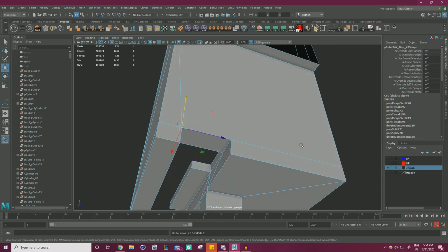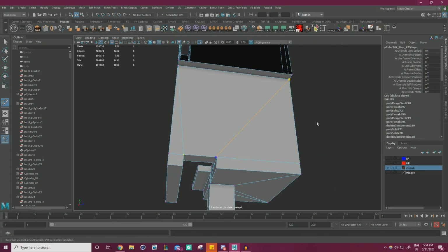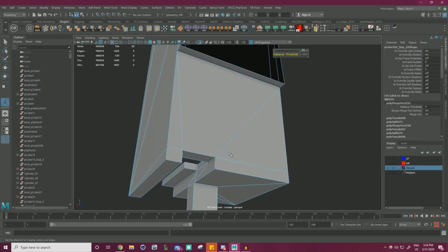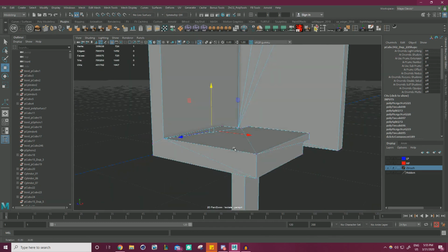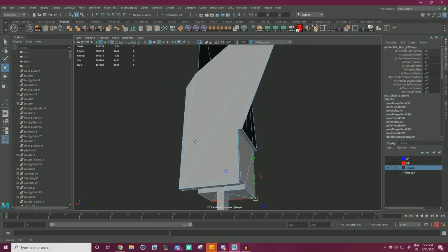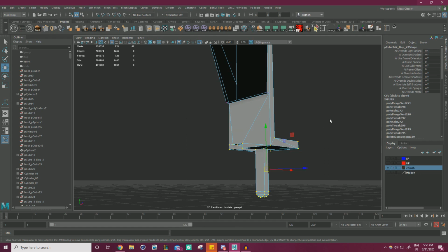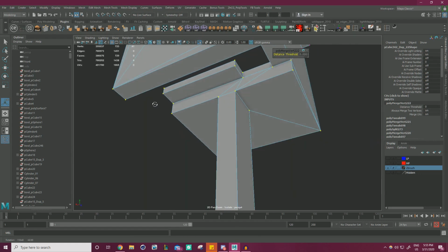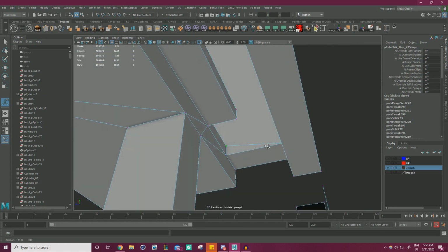Of course, over here, it's still going to be a problem because we don't have a similar situation going on over here. So with those guys anchored down, that should take care of that. The stuff is all as it should be, as long as I snap that down. Yep, that's all proper geo. Just making sure there's nothing that is a face with more than 4 sides, and everything's kind of anchored down properly.